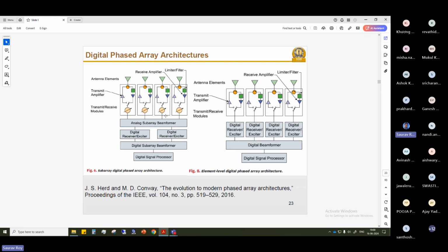Generally, if you want to generate this kind of antenna, it is not only for transmit. We generally want transmit and receive both to be done through the same antenna system. Let's say we don't have space for 10 different antennas, one transmit, one receive. If we want transmit and receive together, that is why you see there will be beamformer ICs and all that comes with half duplex.